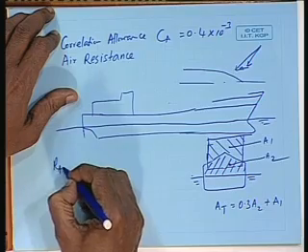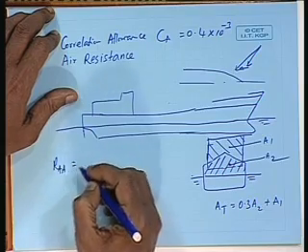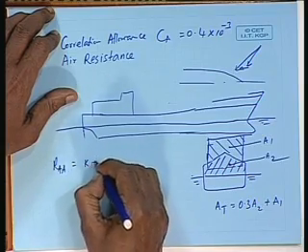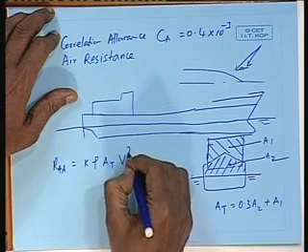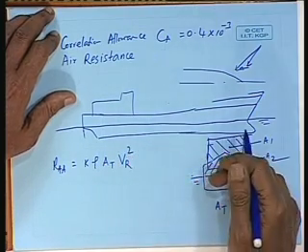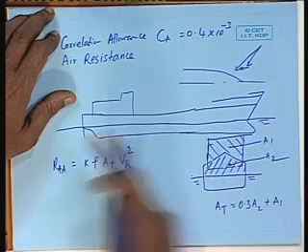So, a lot of people have done wind tunnel experiments to find the wind resistance, and statistically it has been shown that wind resistance R_AA, the normal representation, is R_AA = K rho A_T V_R squared, where V_R is the relative velocity in the direction of the axis.